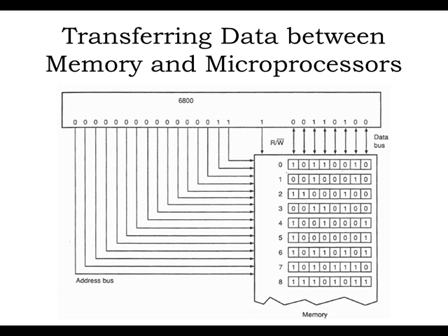Now, what happens when it is read? Let's say this is in read mode, for an example. This is the address, so the microprocessor will be reading from this location. That means this byte of data will be transferred to the microprocessor through these 8 lines. Do you see the 8 lines here? Now, think about it carefully. We exactly have this data here. Look at this, 00110100. That is the exact data you have.